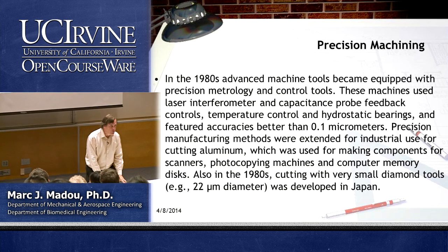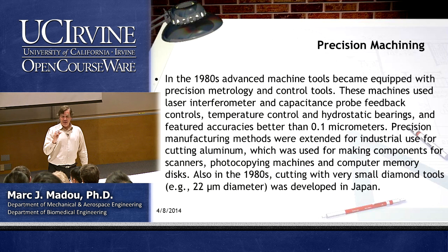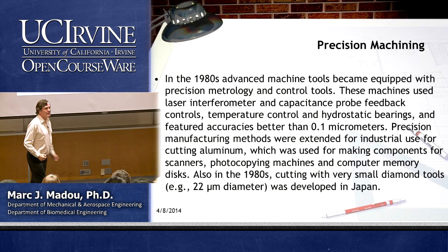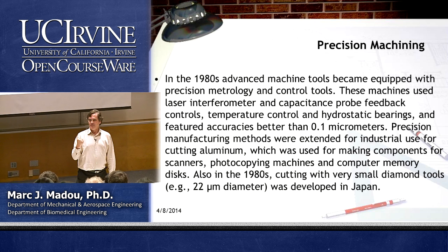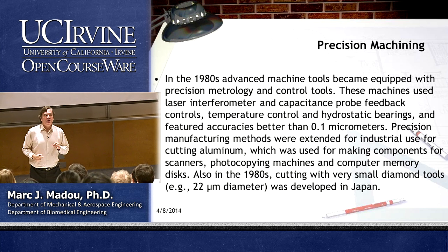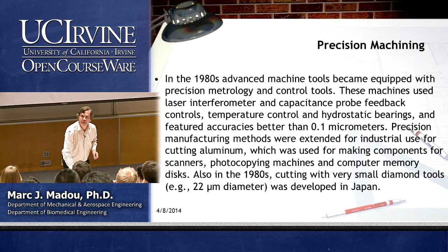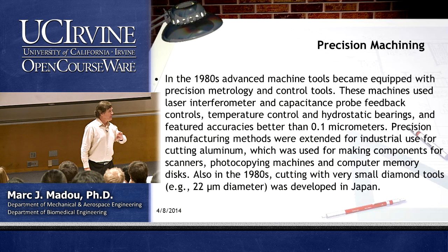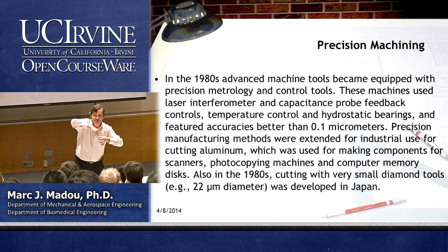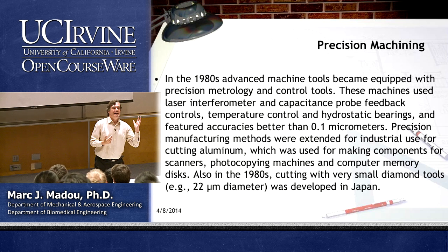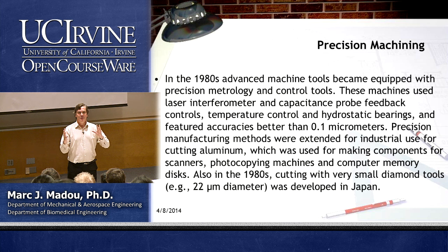We will actually, at the end of this class too, see an example where a mask has been carved out with CNC machining, where features of 1 to 2 nanometers can be observed, can be differentiated. And this is kind of surprising, because you're going to say, look, how could I ever, with a 22 micrometer diameter tool, go to 1 or 2 nanometer? The thing is this. In mechanical machining, you can do tremendously accurate things, but only in one axis, in the z-axis. The cutting itself of the piece will be much bigger. The mask will be, let's say, 1 millimeter. You can cut that. But the features that you carve out in the z direction by going up and down, at different angles, that you can do 1 to 2 nanometers. So when people compare lithography results and mechanical machining, you have to be very careful what you're really talking about.